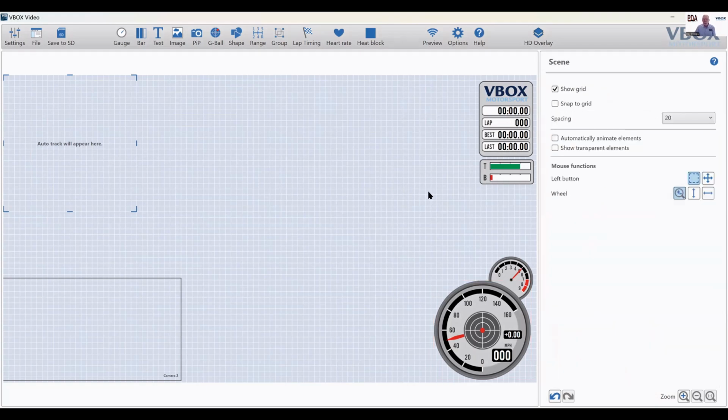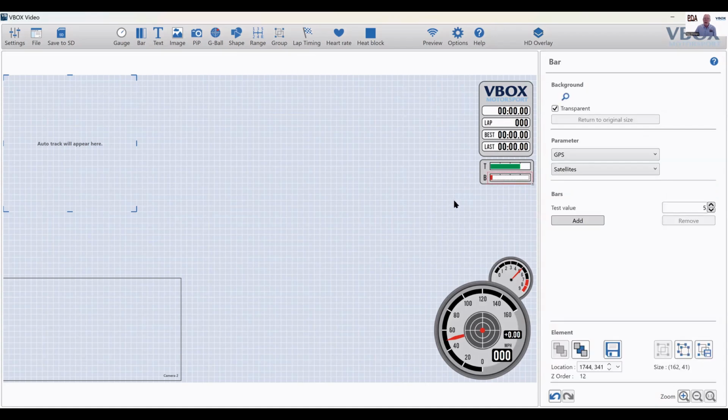So for brake pressure and throttle, I've got to do the same thing that I did with the RPM. I've got to assign the appropriate CAN channels to those bars. It can be a little tricky with these bars. What I've learned is that to click on them, you want to click on the corner, and the red box, it's very light, but you can see it there. It will show you what you clicked on. So in this case, I have clicked on the brake pressure bar.